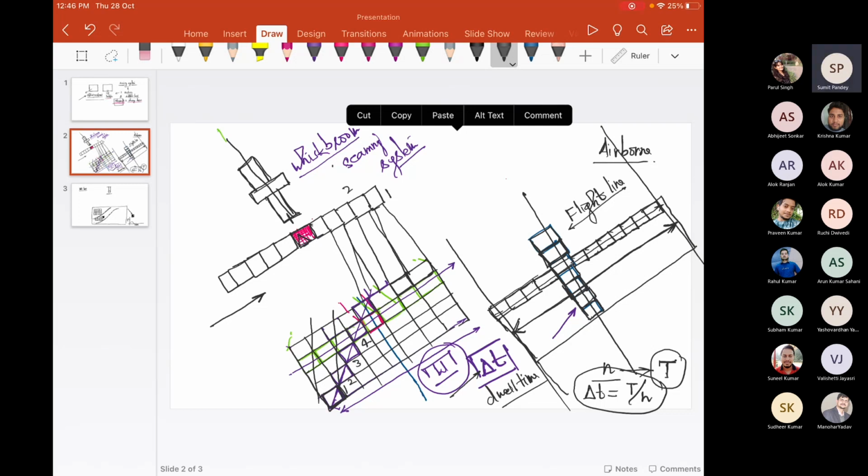if we see in a practical case, though we define a ground resolution cell here on the ground on the basis of the geometry of a CCD, once the energy is reflected back from the GRC, we consider the spread of that energy within the atmosphere. By considering all the factors, we decide the spatial resolution. Because when I say ground resolution cell, the dimension of the GRC is determined by its shape and size.